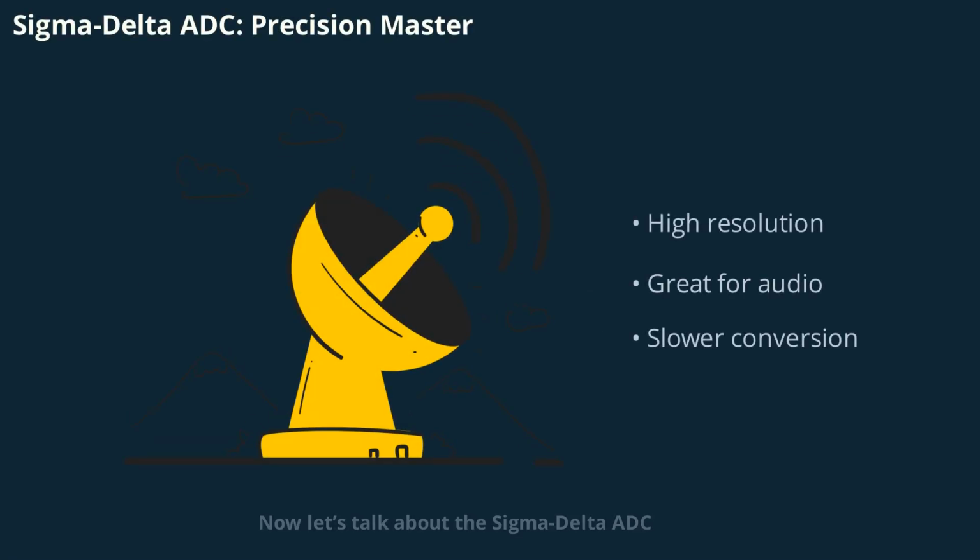Now let's talk about the Sigma Delta ADC. This type is famous for its high resolution and accuracy, making it perfect for audio and scientific measurements. Sigma Delta ADCs work by oversampling the input signal and using digital filtering to produce a precise digital output. They're slower than Flash or SAR ADCs, but their accuracy is hard to beat, especially for low-frequency signals.